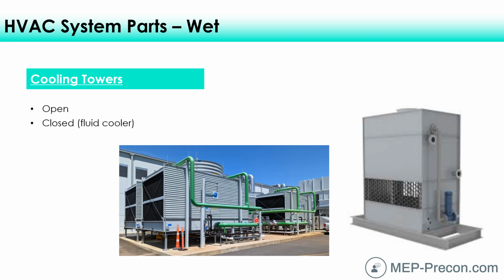That precipitates out in the water where it is the warmest. And where in the system is it the most warm? Well, it's going to be in your chiller in that condenser barrel. And so that's going to collect a lot of these hard water deposits. And what are the implications of that? Well, as that scale tends to build up, it builds up this layer of insulation, essentially, within your heat exchanger. And the more that scale builds up, it prevents good heat transfer. For heat transfer, we want nice, clean surfaces of metal between both fluids.